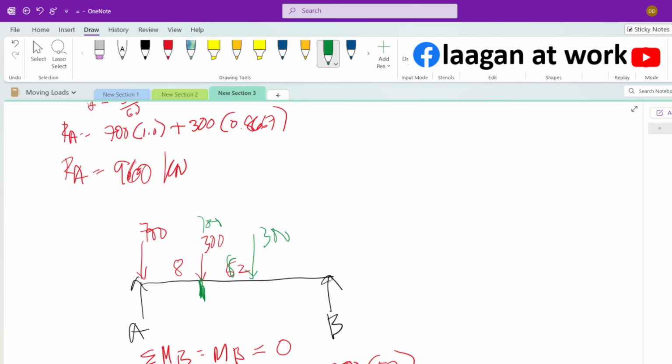That is not the maximum shear at A. If you calculate the maximum shear, you position your biggest load over the support. Now, it's not always like that. It depends. If it's only two axles, then for sure, position the biggest load at one of the supports. But if there are, say, five series of moving loads, then that's not always the case, especially if your total distance between the front axle and the very rear axle is more than this span, then